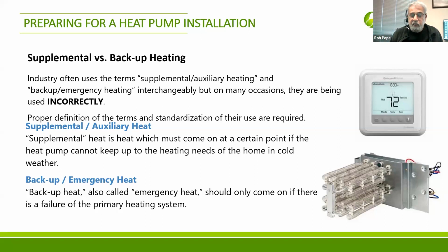Backup heat is a different thing, or emergency heat. That's if the system fails for some reason, especially critical in remote locations. I brought my family up on an island. Getting parts and that kind of stuff was not easy. So it was pretty common practice, whatever kind of heating system you had, to have something to back it up 100%. So it could be a gas furnace, or you could size the supplemental heat to do the full load. It's backup heat or emergency heat. Different thing.